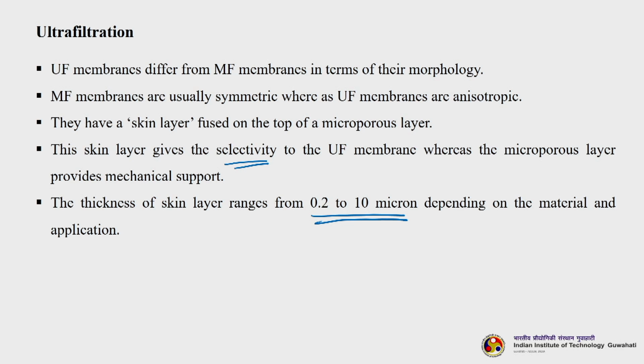But again, you remember, just like in RO, here also the thickness of the top layer, that is the skin layer, must be as thin as possible. Because if it is thicker, then it will add an extra membrane resistance to the overall resistance to the flow of the solvent or solute, which is not good.